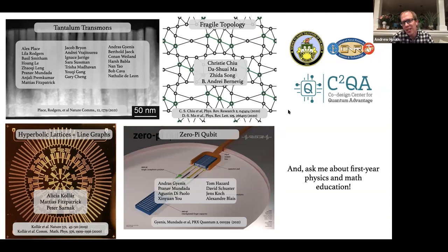Yeah. So I would say, in the Euclidean lattices, it's actually not that big, right? You get quite a bit of the flavor of these with a dozen unit cells, I would say, and that's easily done in 100 resonators, and doing 200-ish resonators is generally not much of a problem for us. You start to run into parasitic modes when you go up to thousands of resonators. But even these relatively small lattices start to realize the physics.